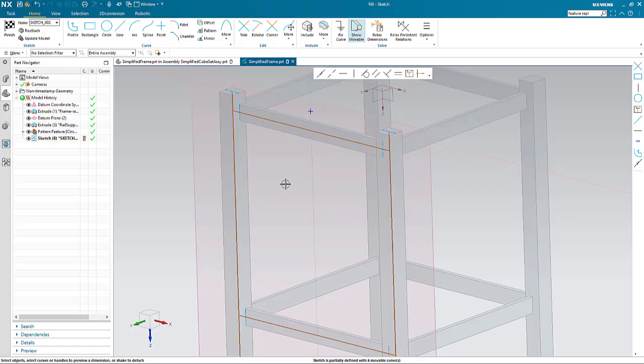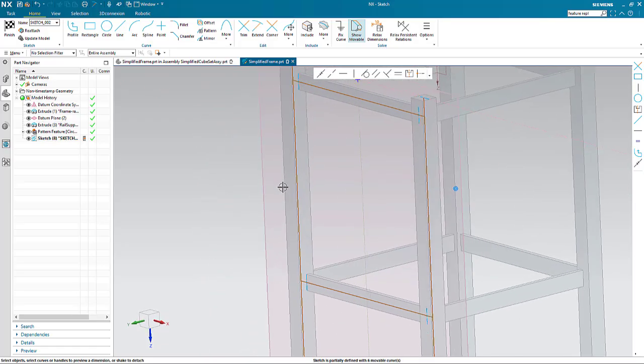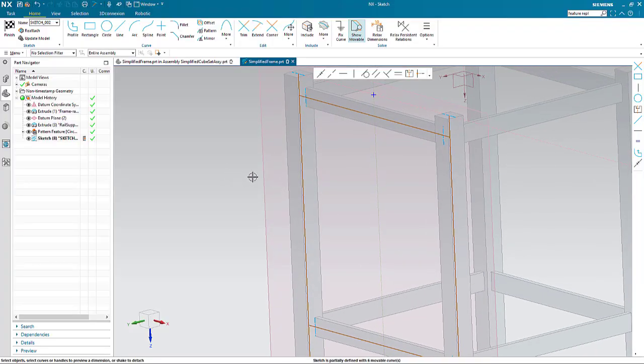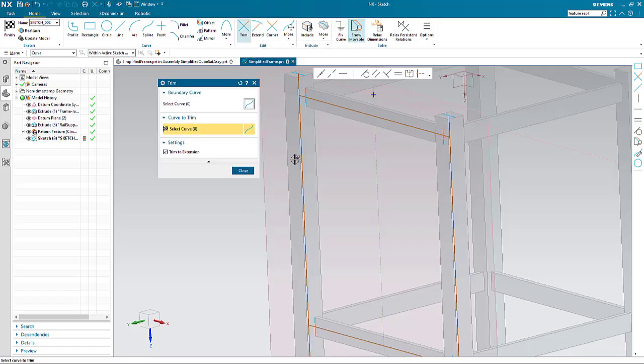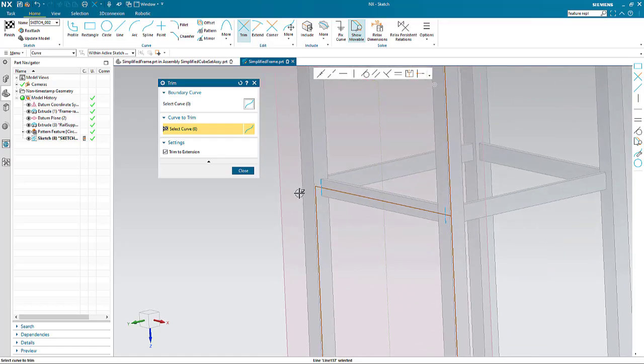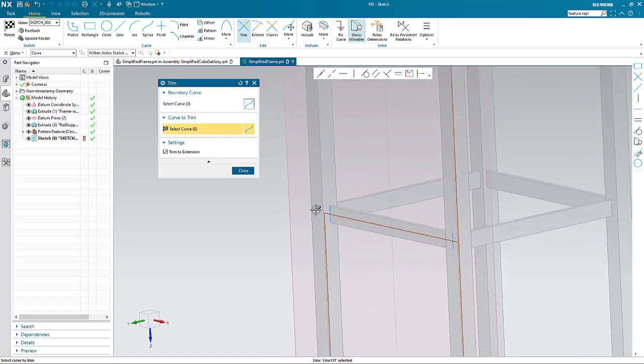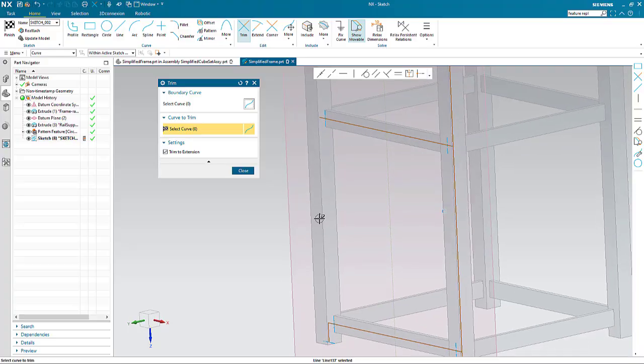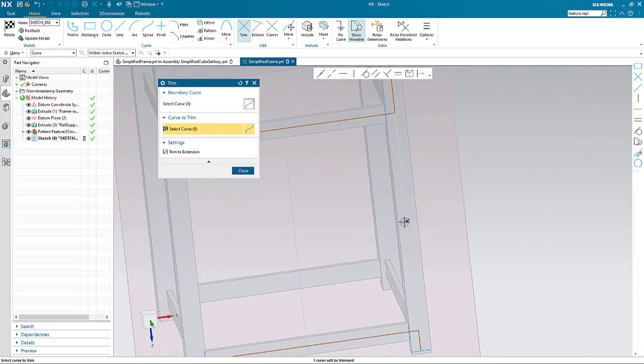Okay, the other thing that I have to do is, it seems counterintuitive, but I don't want to mesh this complete rail, as I want to make sure that I have a break here or a node here so that I get a thermal conductance connection between the rail and each of these support rails. So what I'm going to do is actually trim these. It seems strange to do this, I know. Same with the other side.